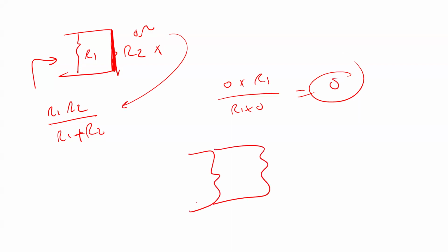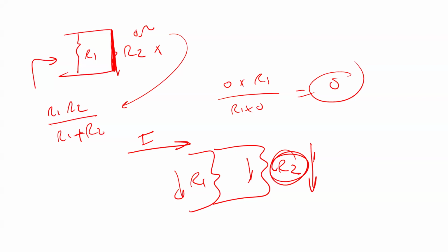In general, if you have two resistors, R1 and R2, and a current I here, this current is divided between R1 and R2. If R1 is equal to R2, it is divided equally. But more current goes to the smaller resistance. As I make this resistance smaller, more current comes here and less comes there, because the summation of the two currents is fixed. When I reach the point that it's 0, nothing will come here because this is an easy path. All the current will come through the short.